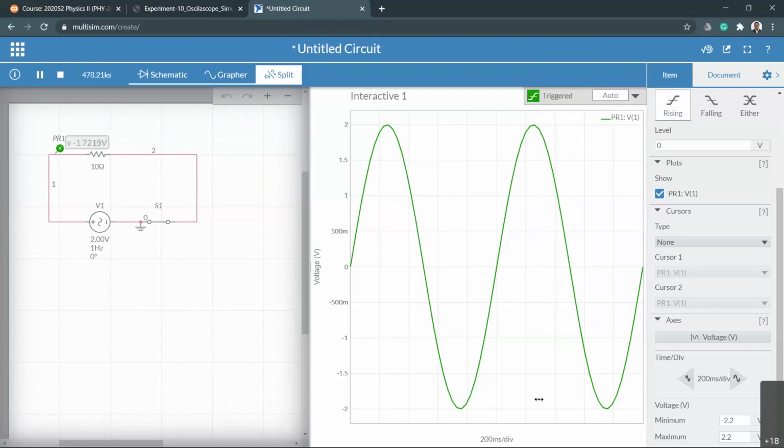Okay, question. All right, let's go and take a look then. Everybody okay with this part? Can everybody observe this? Oscilloscope function and then all the oscilloscope configuration and the circuit. And if the circuit is working fine, you will see this voltage value right here. The sensor should show you two numbers fluctuating because the polarity of this voltage is fluctuating. So that fluctuation should be visible.